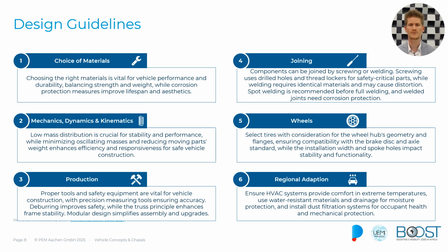Wheels are also very important to look at because they have to be adapted to the road conditions that the vehicle will experience during its use cases. The choice probably depends on the speed you want to go with the vehicle, the loads that we see, and the road surface conditions that the vehicle will operate in. So always bear the tires in mind, and this is something where you can change the performance behavior of the vehicle quite drastically.